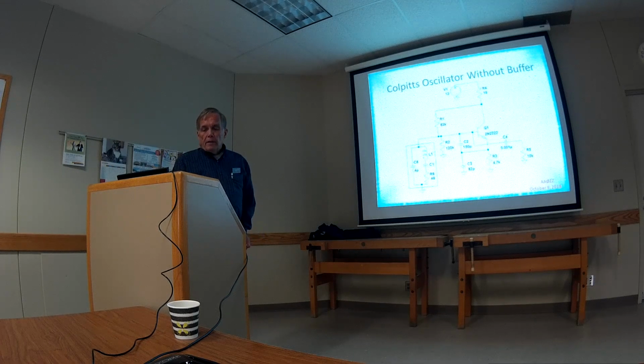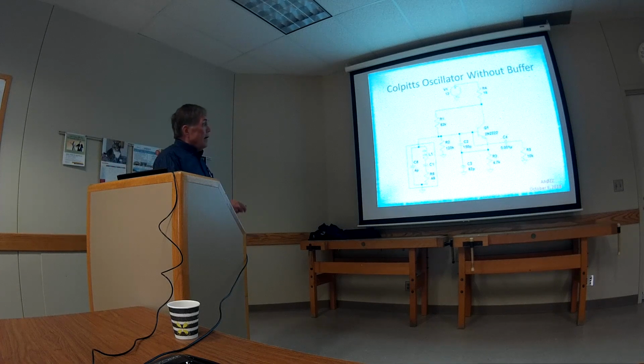But here, this is an LTspice drawing of it, because I want to go through some parts of it. And once again, we see the same 2N2222, a real good transistor part. And the split here, those two values are pretty good for 7 megahertz. And those two for bias, I'll show you that works. And this is how you model a crystal in LTspice.